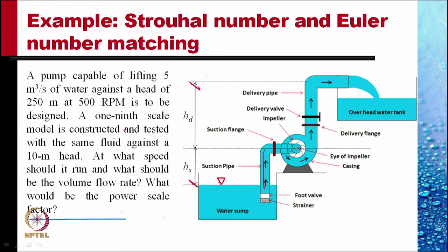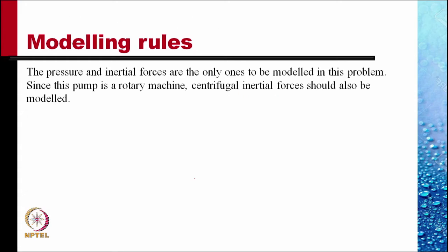At what speed should it run? And what should be the volume flow rate if there has to be similarity? What would be the power scale factor? These are the questions that need to be answered. The pressure and the inertial forces are the only forces that one needs to model in this problem. Since the pump is a rotary machine, centrifugal inertial forces should also be modeled.